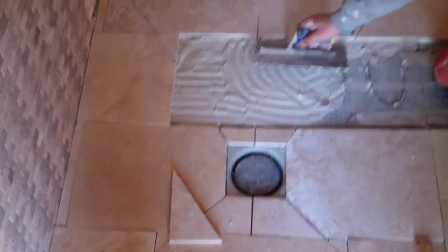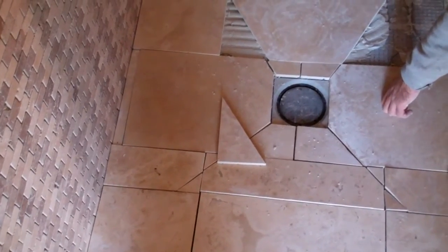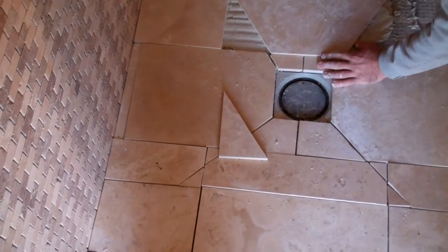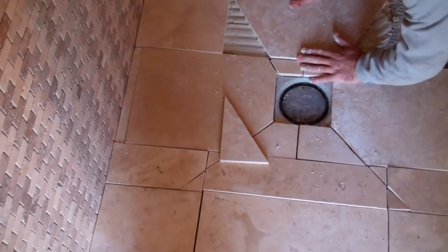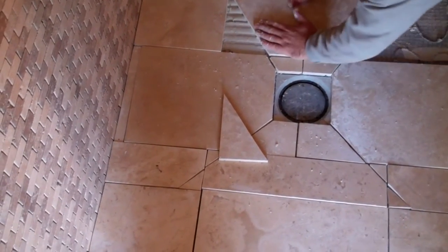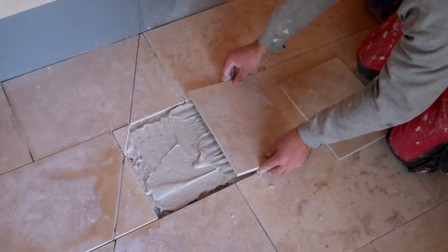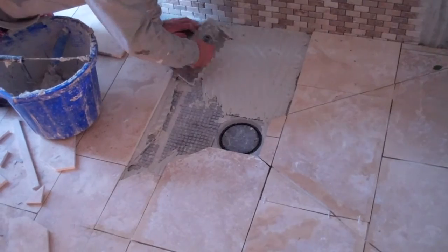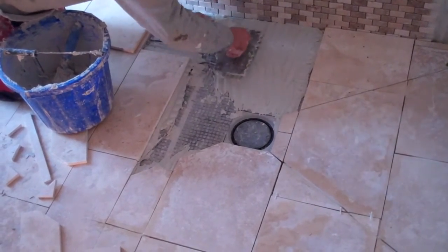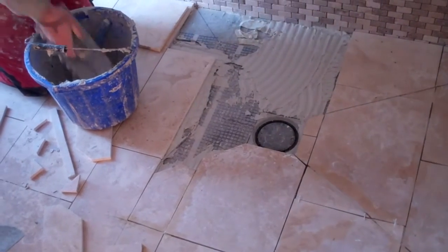When all the tiles are cut to size, fix them into place with a normal, flexible and waterproof tile adhesive. This tile cut pattern is more complicated than most because the floor tiling was installed in an offset brick style pattern. Care must be taken when applying the tile adhesive to the slope to falls area. Ensure the thickness is even and the full slope to falls is maintained. The tiling in the rest of the wet room is applied in a normal manner.